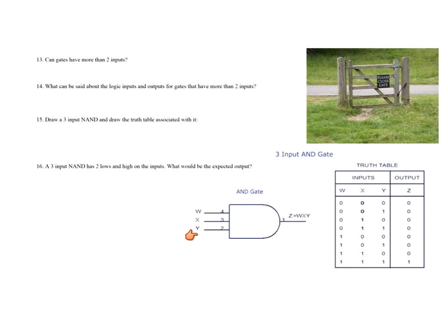So here's a 3-input NAND. What would that look like? Well, this is an AND gate, and this is the output of the AND right here. And how would I make this into a NAND gate? Well, I would put a dot on the end, right? That would be represented by this dot on the end. And then if I was to go over here and draw the output for the 3-input NAND, what would it look like?